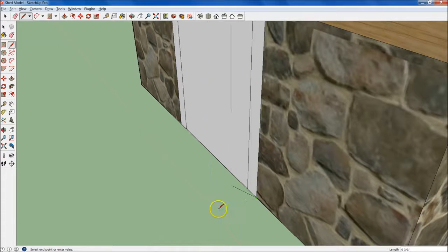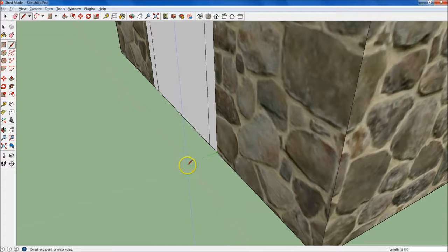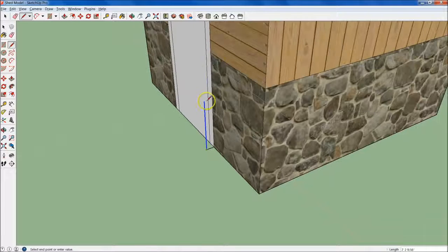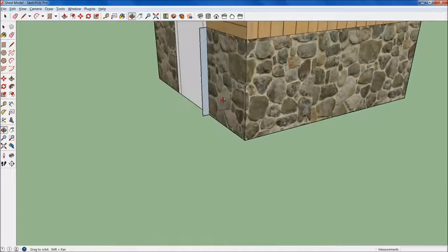And so what we're just going to do real quick, just push that back out of our way. If you did the trim on yours, yeah, just push it back and we'll pull it back out a little bit later. In fact, I'm just going to come out 6 so we don't have to worry about extruding any later. Let's do 4. Yeah, 4 is fine. And we'll come up, line it up. So now we're going to use the follow me tool.